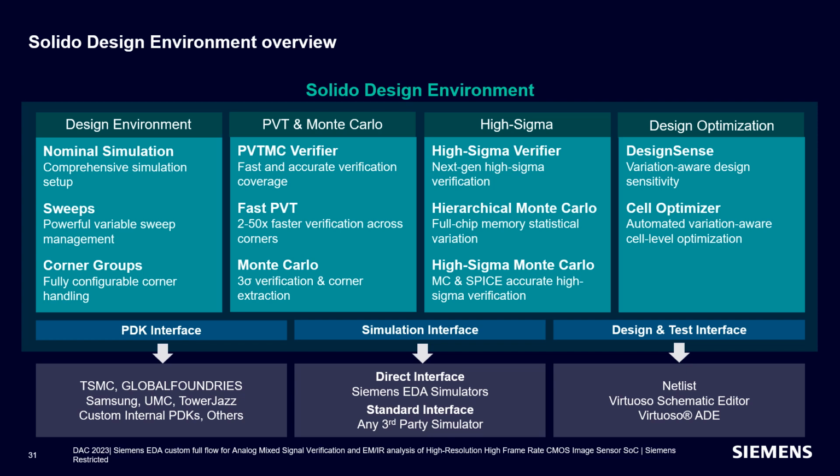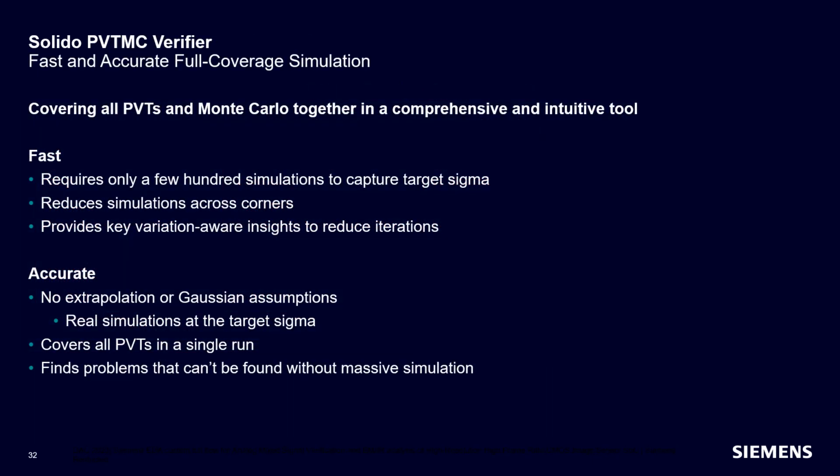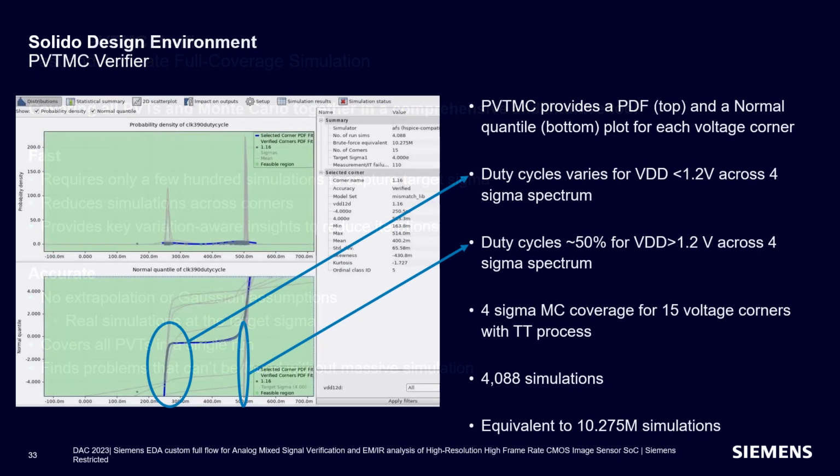Additionally, high sigma verifier tool can be leveraged for doing very high sigma verification for critical blocks where yield is extremely important. In the subsequent slides, I will cover one test case each with PVT-MC verifier and high sigma verifier for our block level circuit design in image sensors. First, we will start with PVT-MC verifier.